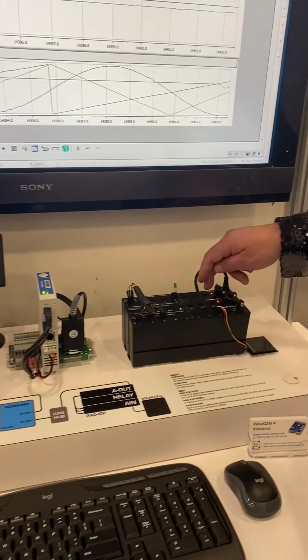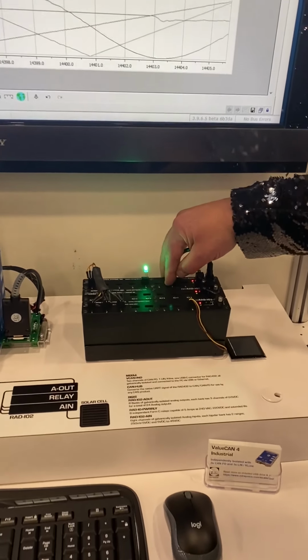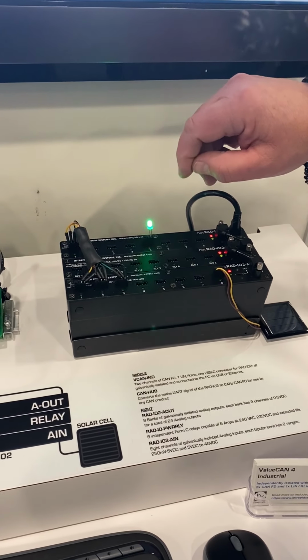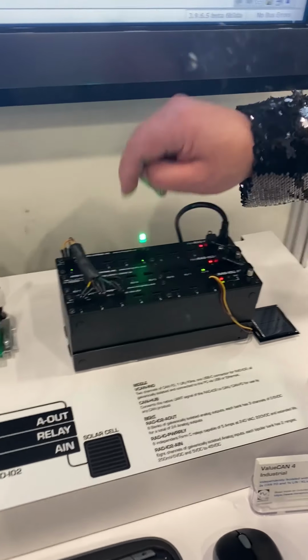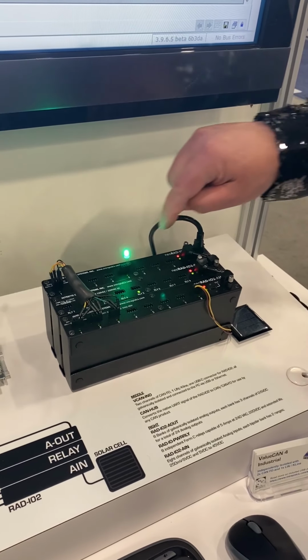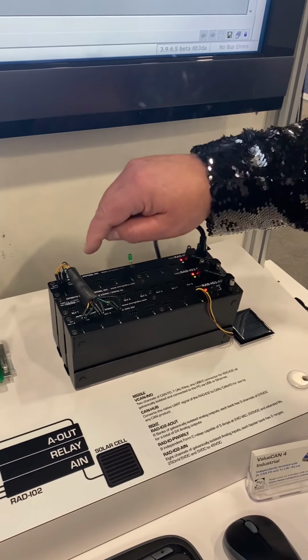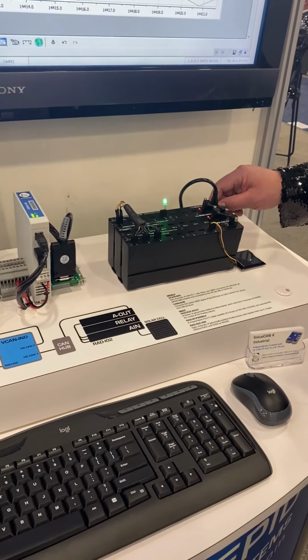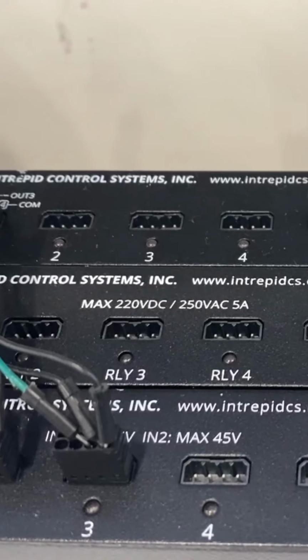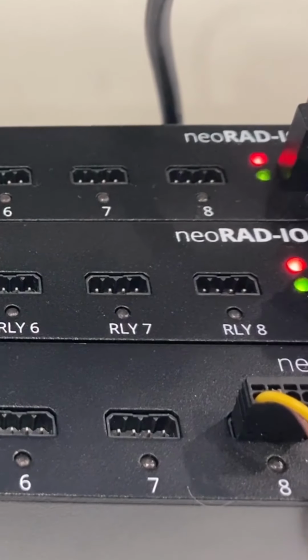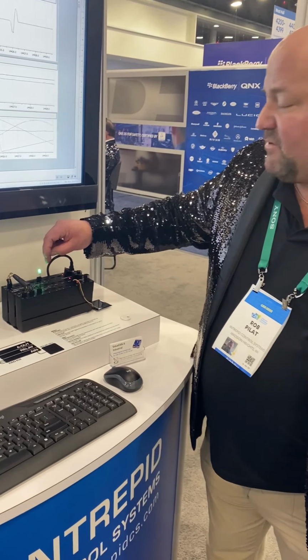And as far as the relay section here, the analog outputs go, there's 8 banks of analog output. Each bank has 3 analog outputs, 0 to 5 volts. You can cascade these and actually generate 40 volts out of this, and then you could cascade further modules to get almost anything you want, up to 1500 volts. That would be a very easy way to do battery cell simulation.